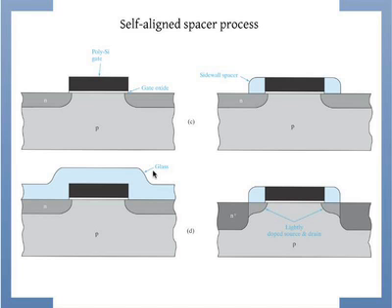Okay, you remove the oxide. Now, what happens is that the oxide over here is thicker vertically than the oxide over here and here. So at the end of the day, you end up with some silicon dioxide remains. Okay, now you have created these silicon dioxide barriers without actually doing any lithography.